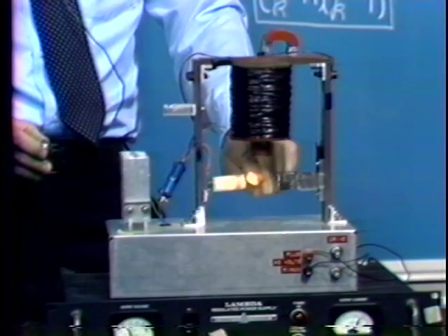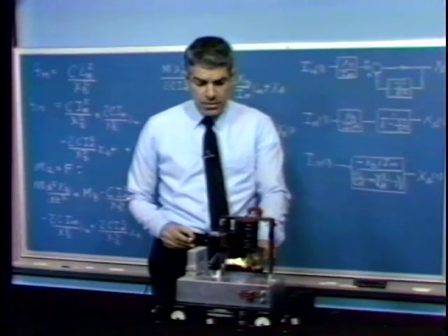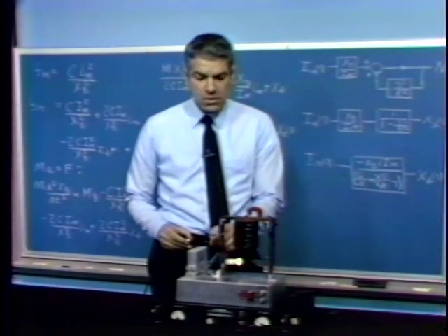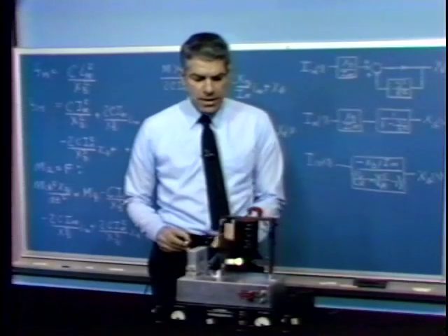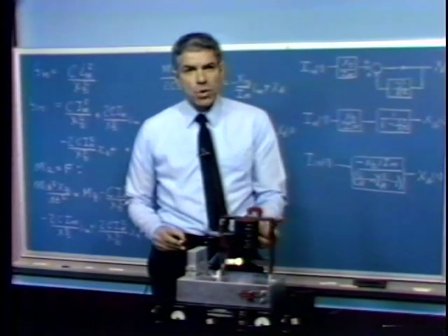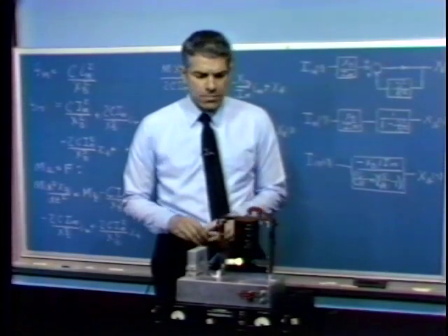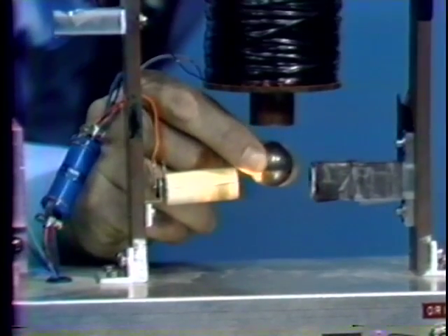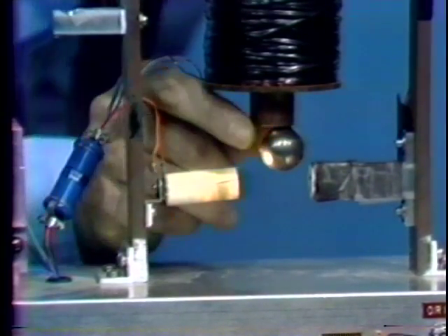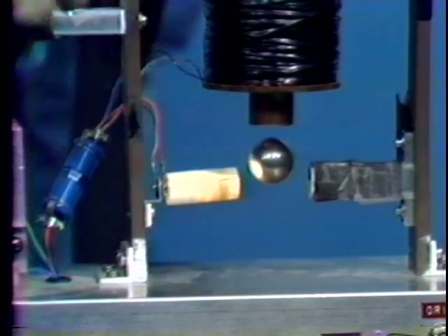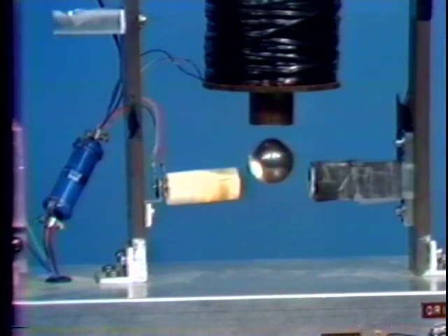When we notice that the ball has dropped further down, is falling away from the magnet, the system reacts so as to increase the magnetic strength. Conversely, as the ball moves up, the system works to decrease the strength of the electromagnet. And if we do all of that correctly, we find out that the system will in fact support the ball in the magnetic field.